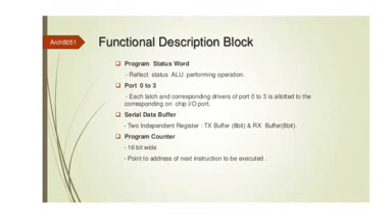And apart from this you have one bit reserved for future purpose, and one user flag bit. You have two more bits, D3 and D4, that are register bank select bit 0 and register bank select bit 1. Why and where we use these two bits, we'll see when we talk about the internal RAM memory.